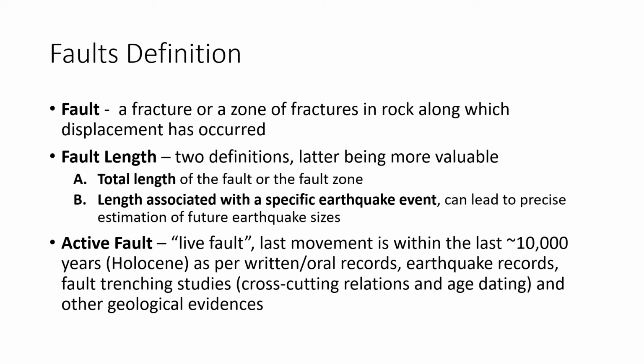So for example, I think the Bangui fault in Ilocos is approximately 200 kilometers long, but in the event of an actual earthquake, it's very unlikely that the whole 200 kilometers will actually move. It is more typical for just a portion of the fault to undergo displacement during an earthquake. Okay? So length is important because it has implications on the magnitude of the earthquake, which we will be discussing later in the other lectures.